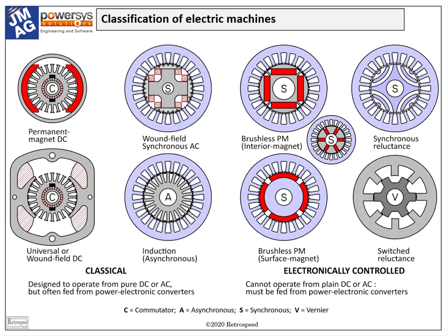We will see that magnets are used in several important types of electric machine. If we take them away, we will have to use machine types from elsewhere in the diagram. In the important class of AC drives, the ones colored blue, fortunately, there are some viable, proven alternatives: the induction machine, the wound field synchronous machines, and possibly the synchronous reluctance machine. All these machines share the same power electronic controller topology and, to a large degree, a common control methodology.